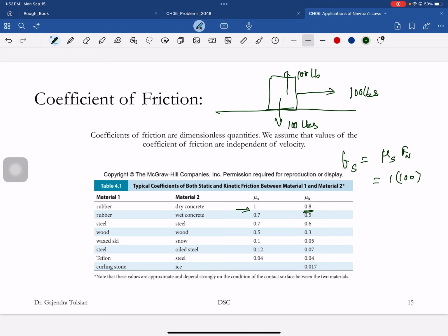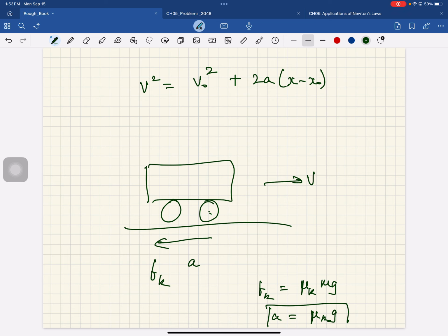Okay. Well, what does that mean? Okay. So what you do is, when the wheel is rotating, see this point, so when you're trying to slow down, the wheel will want to rotate that way, and this point is in contact and the contact point is preventing it from sliding, the static friction force will be in that direction. Okay.